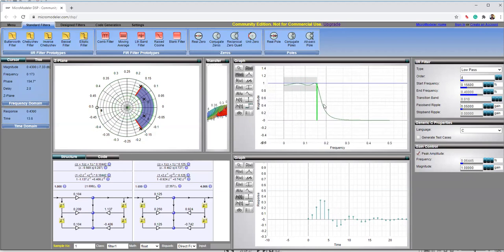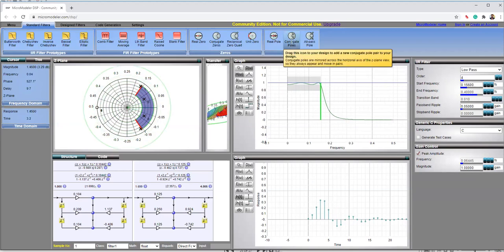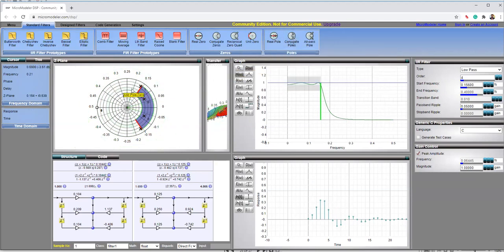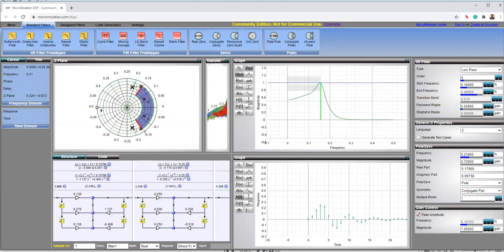So now let me introduce some poles here arbitrarily. I want to introduce a complex pole. So I'm introducing an artificial complex pole there. Now can you see the changes? By changing this one, I can interrupt. So what could be my desired filter? It does not look very good, so I can change it. Always, filter design is a trial and error method.